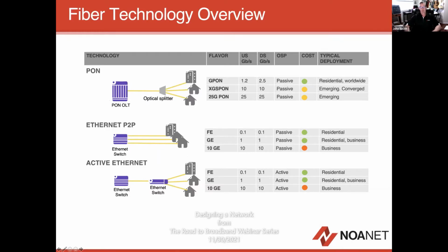The one important thing going in is you need to know what you're going to use, which of these technologies you're going to be using, because your fiber counts, the locations of your cabinets, the requirements for your cabinets, the power, the batteries, all are going to help determine what the outside plant looks like. When I say outside plant, I mean the fiber that's being hung on the poles, how big those fiber cables need to be, how many fibers need to be in that cable to serve a neighborhood and the neighborhood down the road. So you can't build the fiber and then come back and decide which of these you're going to deploy, or you're going to be in trouble, especially if the person putting it in is thinking this and you decide to do this. You're not going to have near enough fiber and you're going to have to overbuild yourself. So it's important to plan for the outside plant, even though it's the first thing that goes in. You need to know what you're going to be lighting it with when you're finished, in order to make sure that it is designed in the most efficient way.